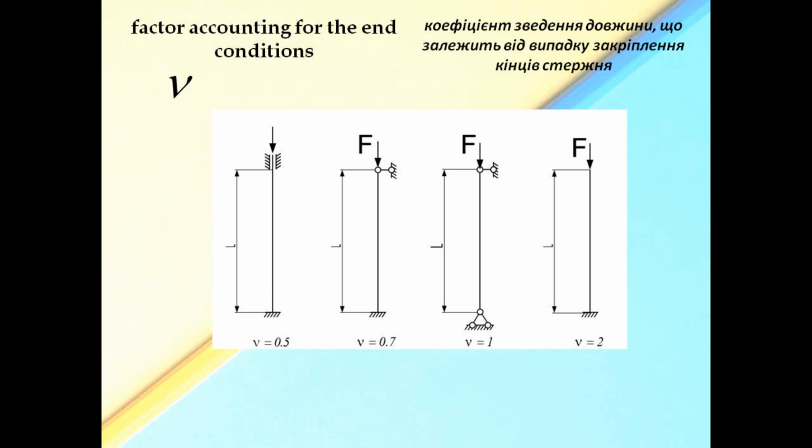If both ends are fixed, then the column cannot rotate at its ends. It bows in the center relative to two inflection points located length divided by 4 from each end, so the effective length of the bow is half the column length.